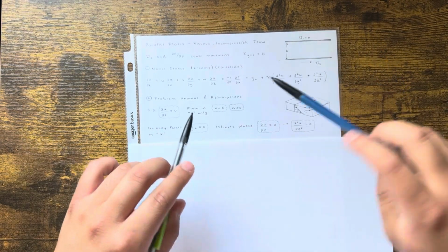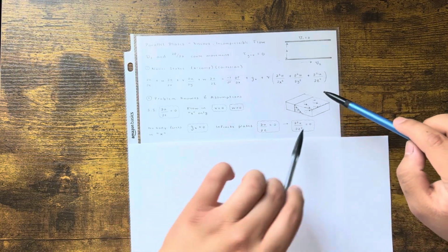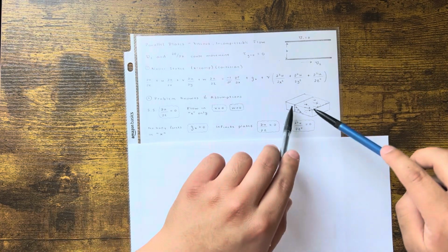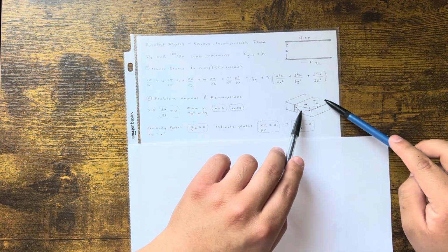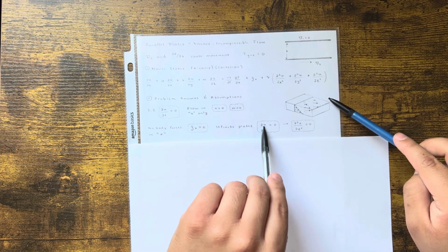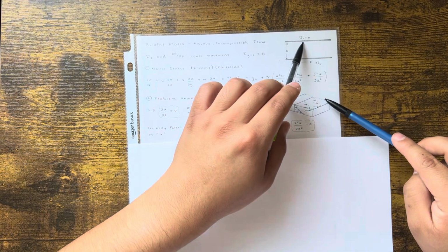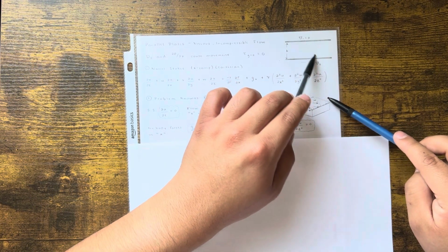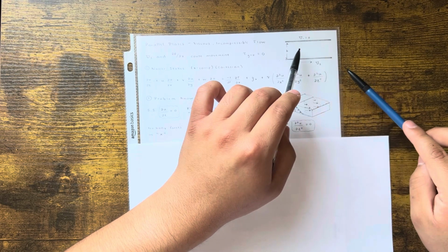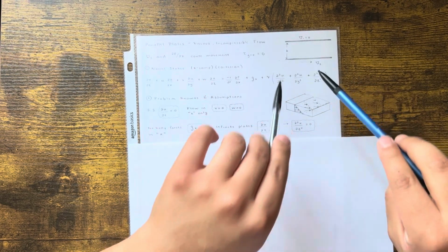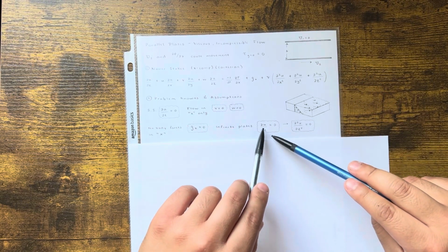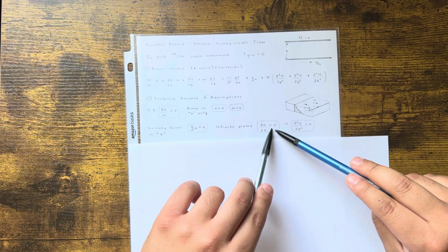So that's 0. Infinite plates. This is what I like to draw for infinite plates so I can help you guys see it better. The profile here is the same going into the paper. It doesn't change with respect to Z. So the velocity U is going to be like a parabolic curve, or it could be a linear curve. Velocity is flowing constantly to the right, but going into the paper, it's always going to be the same. So that's what that's saying. Infinite plates, that's the assumption. Delta U over delta Z is equal to 0.